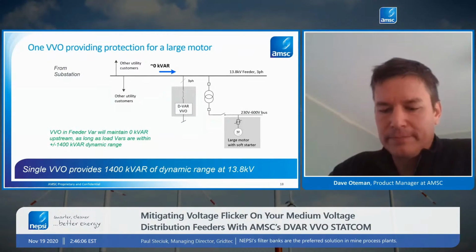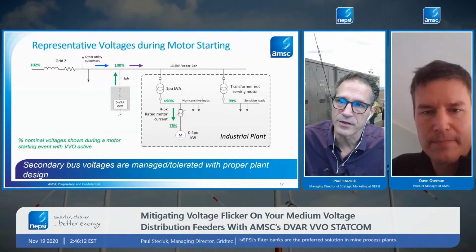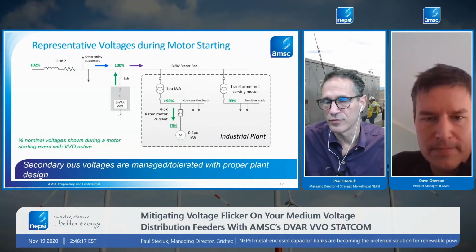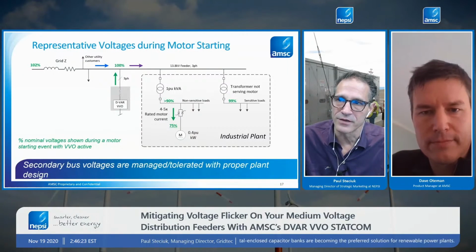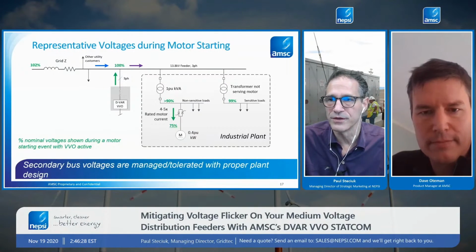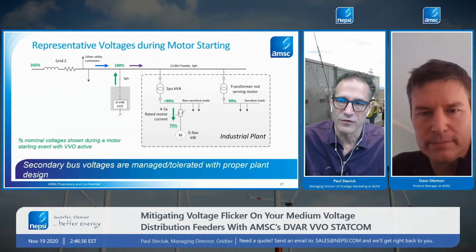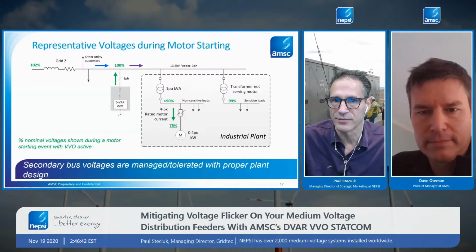My experience, Dave, is that what I've typically done is no more than a 4% voltage drop on the primary and no more than a 10% drop on the secondary would be my basic design principle, with the understanding that the utility might not give you 1 per unit voltage. They might give you maybe 0.95 per unit voltage, which means the customer's voltage at the motor during starting might even drop to 85%. And most of the time, you see these torque speed curves drawn for motors, 85% is the value that they show. So that's how I derived that 90% number as a target design value.